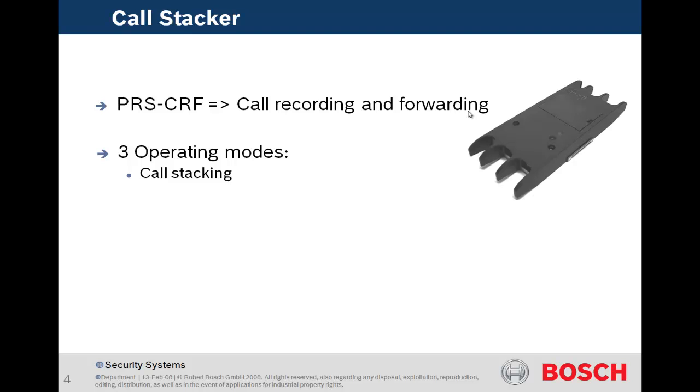Call stacking, which is essentially just handling collisions in the system. Time shift, which is also known as forced stack. If I'm in an area where I've got a speaker above where I'm paging from and it's going to feed back, I have the ability to force the system to record my live page, and then when I let go of the page button, play back that page immediately, getting away from any kind of feedback issues.